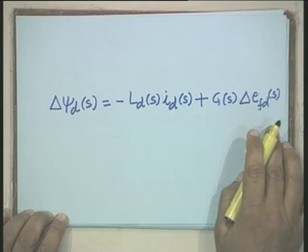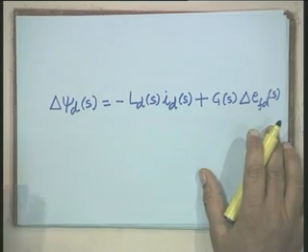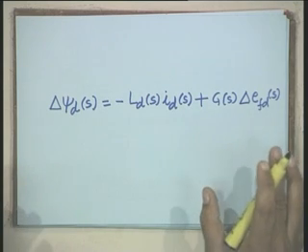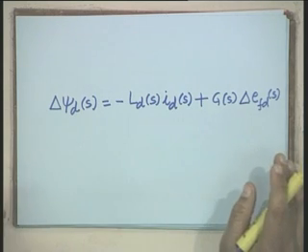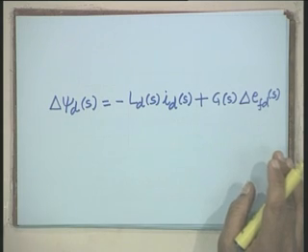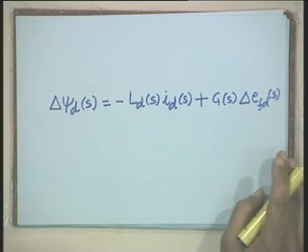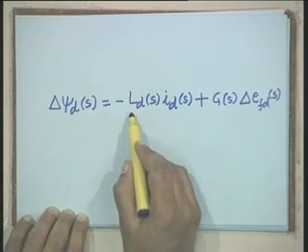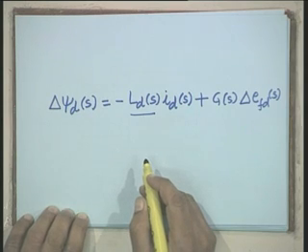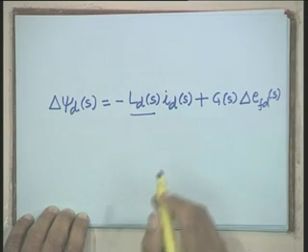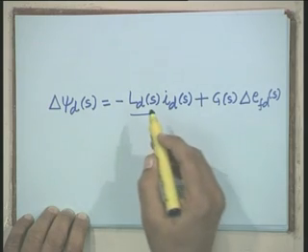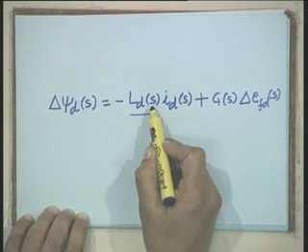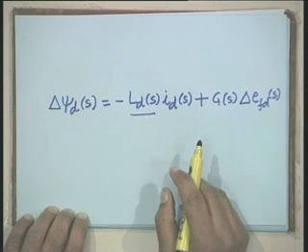This is a very standard way to start with. We are trying to relate the current, flux linkage and the voltage applied at the field winding of the synchronous generator in terms of what we call the operational parameters. That is, this Ld(s) is the operational direct axis inductance. We understand the meaning of operational here, and this parameter s which I have shown here is the familiar Laplace transform operator.